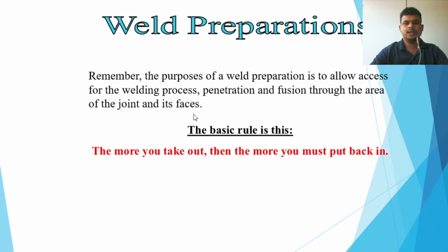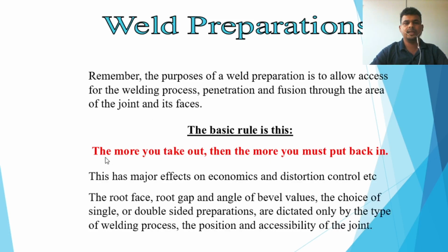The basic rule in this, you need to remember also, the more you take out, the more you must put back in. That means if during weld preparation you do more bevel preparation, then you need to refill all this space with filler metal. So if you take out more, you need to put back in more. This has major effects on economics and distortion control, etc.